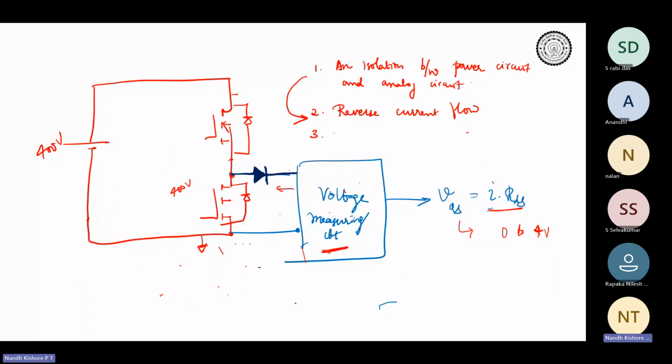During that time, I'm not going into the measurement circuit, but if we go into it, you might be able to understand it even better. When 400 volts is coming over here, as far as this measurement unit is concerned, it will just sense the voltage. It doesn't know whether the device is turned on or turned off. You need to have some mechanism for that as well. So when 400 volts is coming over here, it will sense that across the device a huge voltage is coming, much greater than whatever limit you will set. Let's say you set a 7 volts limit as the overcurrent limit.